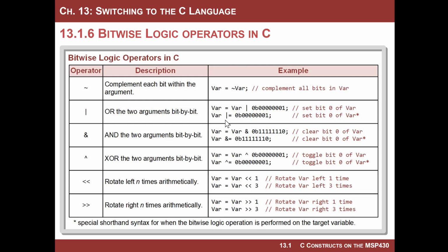And so you have to go into the configuration registers, figure out which features you want, how to enable certain things, how to clear certain bits, how to enable interrupts, clear flags, change the source of clocks. It's all done with these bitwise operations. And we are now in C, so we've got to figure out how we do those.